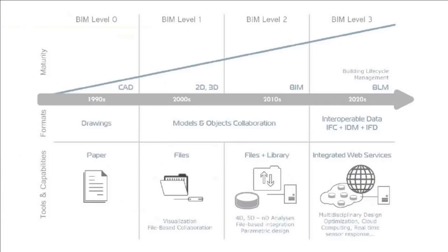I think for landscape architecture, out of the box, I have never worked in Revit. I don't know, but from what I know about other people and hearing stories, out of the box, Vectorworks has more tools ready for you to use, whereas Revit requires you to build those in what they call libraries and components, because Revit's more geared for architecture.